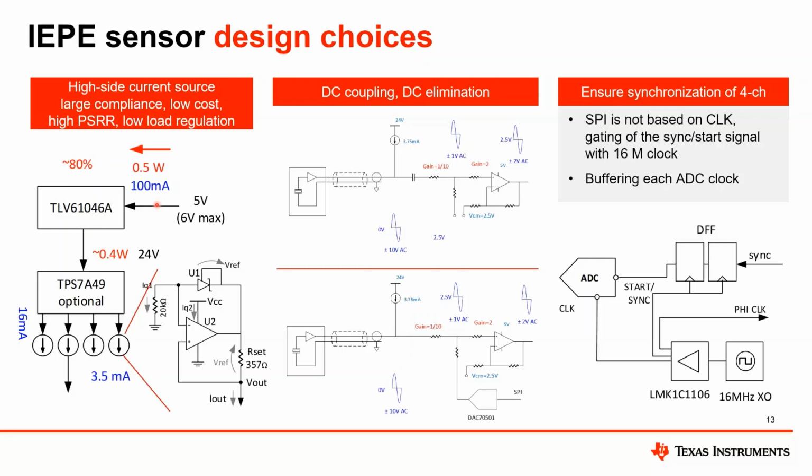Half of that is going to generate the current sources at high compliance voltage. And we remember that we need that high compliance voltage because of the sensor. If the sensor is generating a high swing signal, plus minus 10 volt, we would need the high compliance.